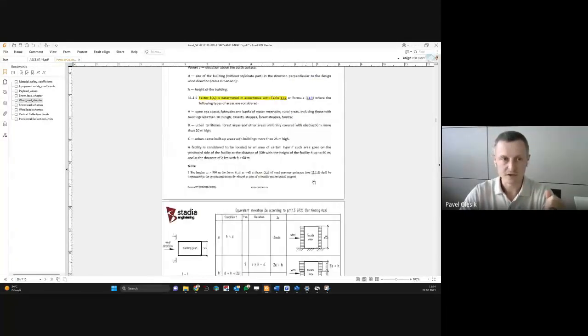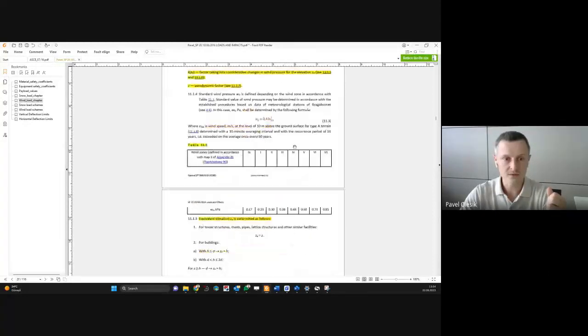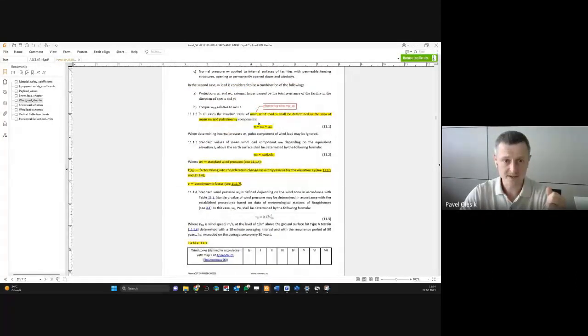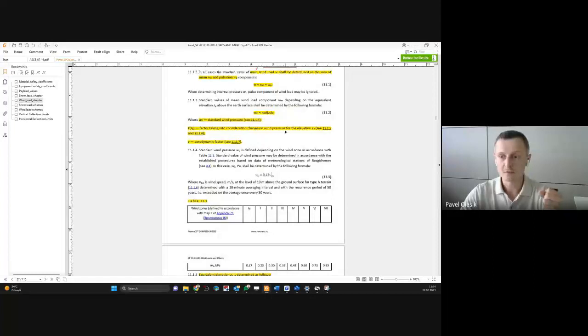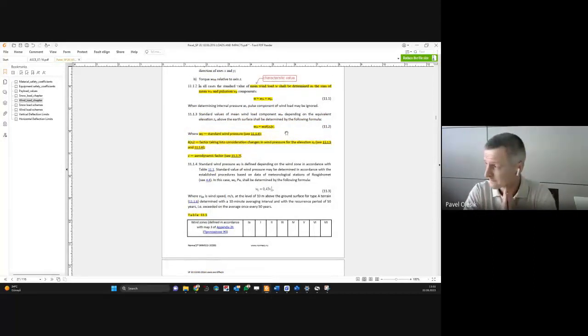So wind load must consist of two different components: this basic load and pulsation load. Please check it all the time. Usually for small structures such as technological platforms, secondary structures, I am taking double basic load for the safe side, and do not check pulsation load. But for important structures such as residential buildings, for some huge structures, we must calculate it correctly.